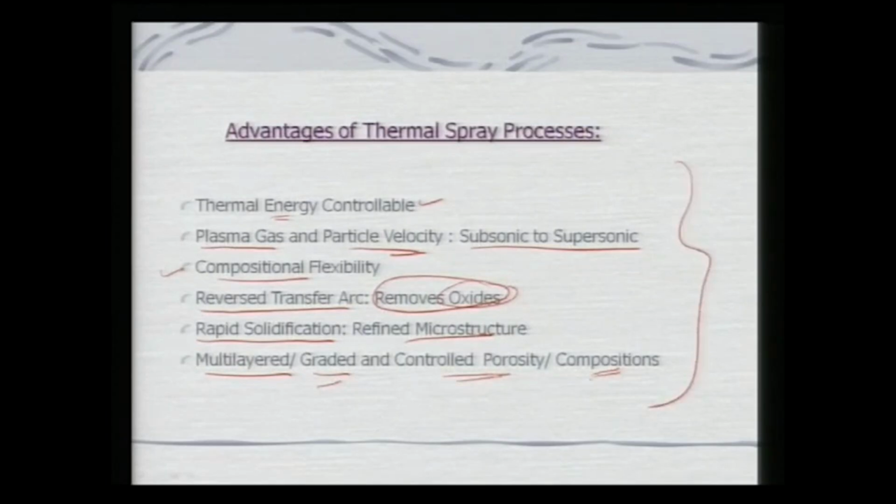When we require a graded porosity, so that the cells can really extend their arms and anchor to the coating material, that is very essential in terms of bio coatings. They need some interaction with the surrounding cells. So, cells can extend their arms into the pores, and then they can enhance the overall integrity with the device or the implant material.